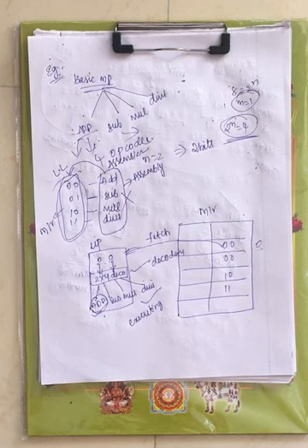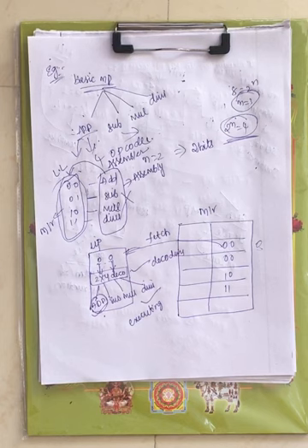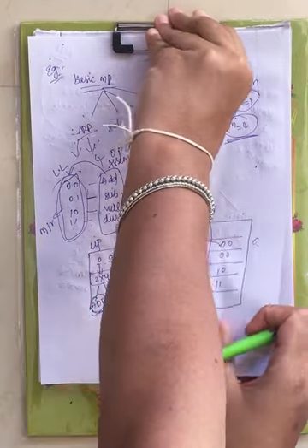First it will take the opcode from the memory, and next that is given to the decoder. The decoder will decode it, whether it is addition or subtraction or multiplication or division, based on the fetched opcode. Then it will get executed, right? Here it is fetching, decoding, and here it is executed. This is how the basic processor works, just a simple processor we have considered: fetching the opcode, decoding that, and after that executing, right?